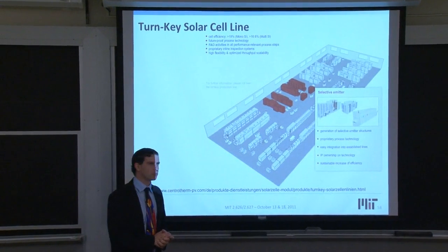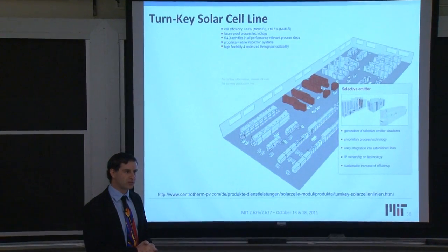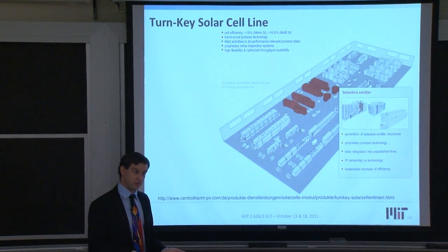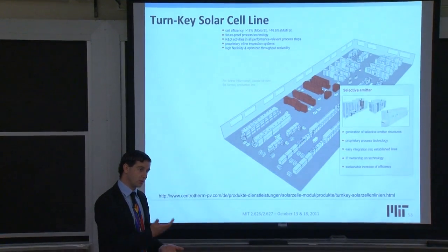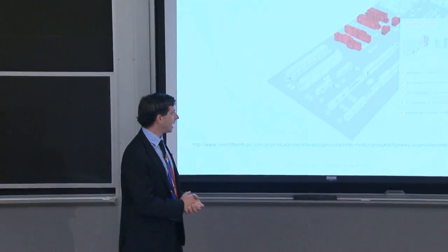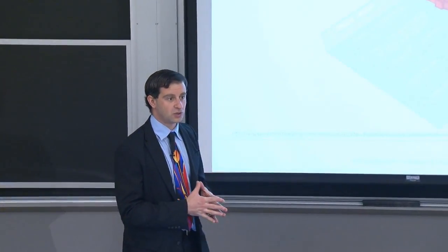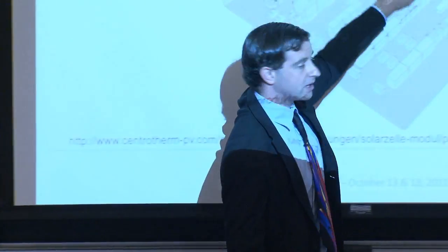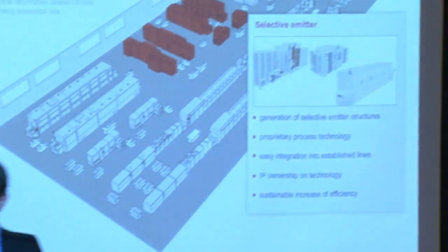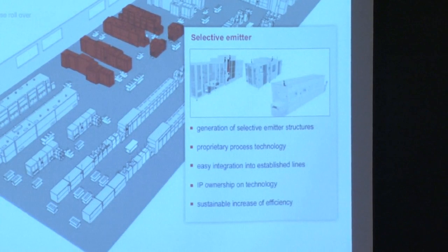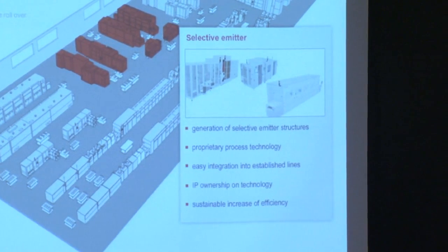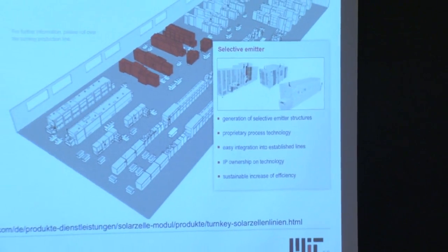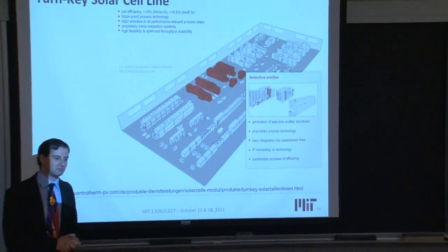One involves creation of porous silicon on certain regions of the wafer that you want to etch back and create the shallower emitter, leaving the deeper region intact. You could use a form of shading, you could even use a wax. There are a variety of technology options for achieving that goal. But in a sense, many of the selective emitter designs involve a deep diffusion first and then a partial etch back. For example, creation of porous silicon and then etching that material away.